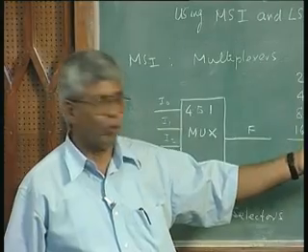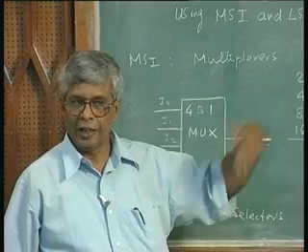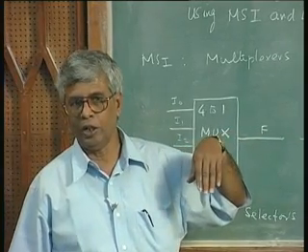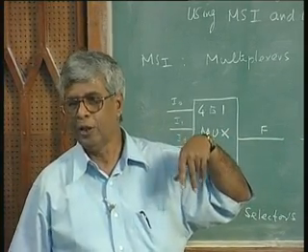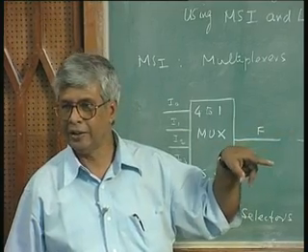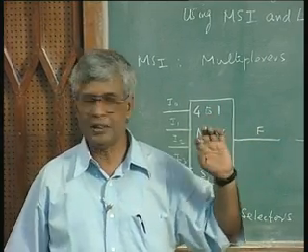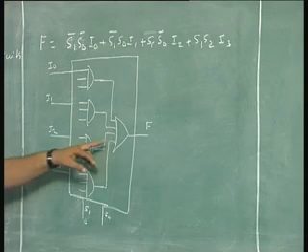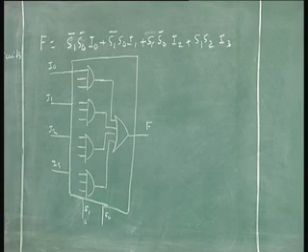But instead of buying these 4 gates, 3 input AND gates, 2 inverters and 1 OR gate, which will be how many ICs? Because an OR gate and an AND gate will not exist in the same IC. Naturally, I need to buy 1 IC for this.